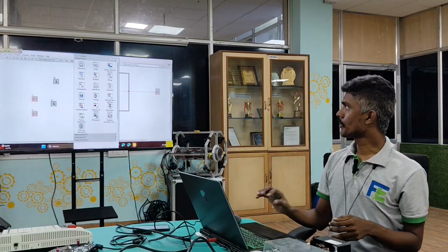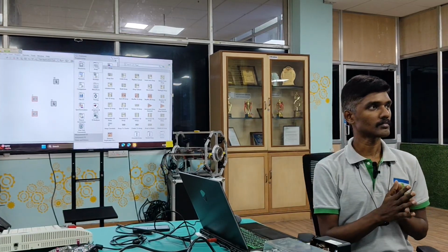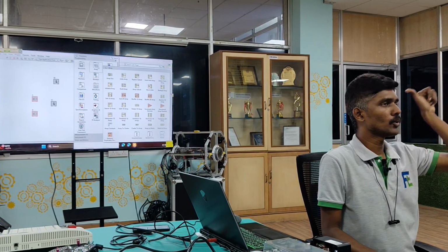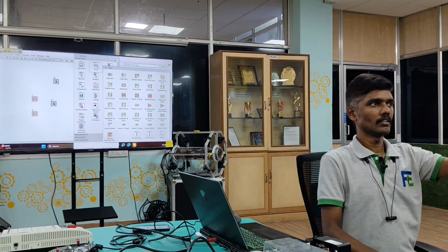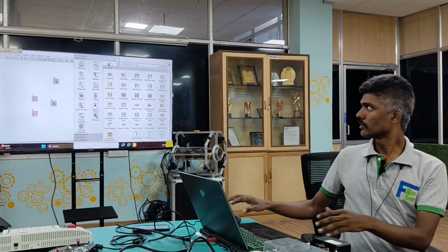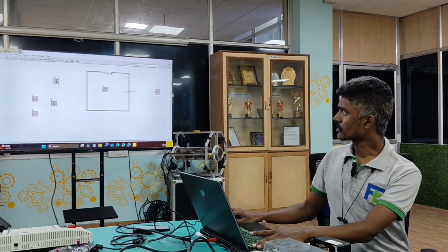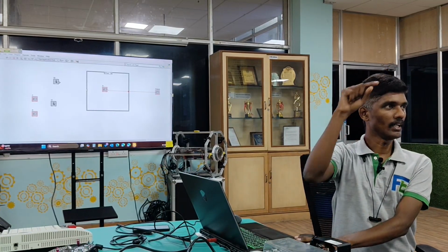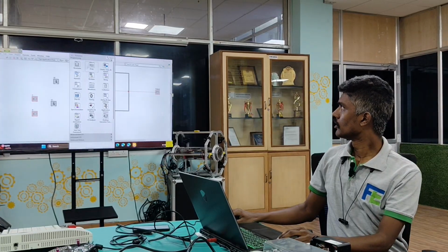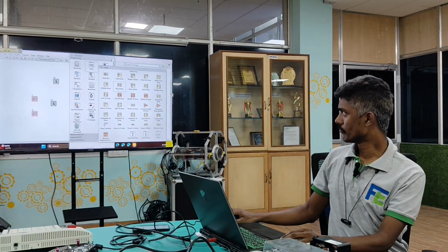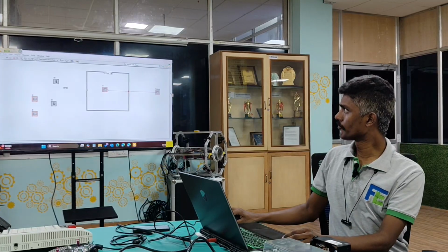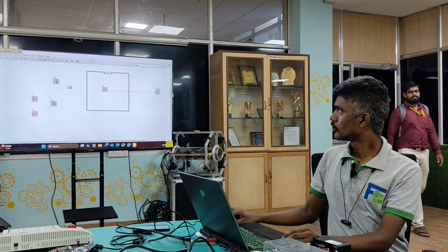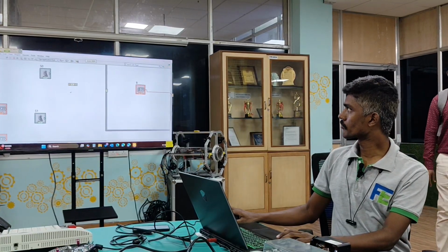We can go to the array subpalette. If I connect S0 and S1 individually, I need 2 wires. But if I convert them into an array, I will get only a single wire. So I will do the conversion of the wire to an array. Delete the wire between your S0 and case structure first. Once you delete this, go to array and then build array. Build array looks like something like this.